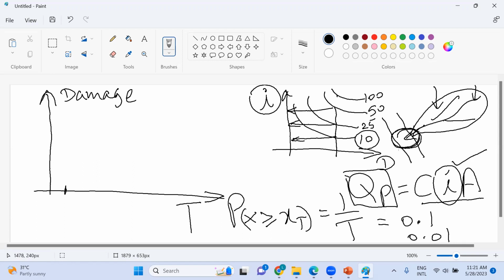Why is it? A smaller return period means you are talking about a smaller peak flow, so now you are talking about a smaller cross section. If you have a very large or very intense rainfall event in the upstream, probably this cross section now will not be able to handle this water flow. So what happens? The area starts flooding, right? So the damage can be very high.